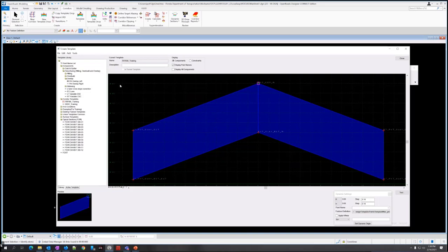So now we need the resurfacing. This is the overlay component. So we're going to go to the milling component. Sorry. So I'm going to drag in the pavement milling right, and it's going to snap to the pavement overlay underscore bottom in.